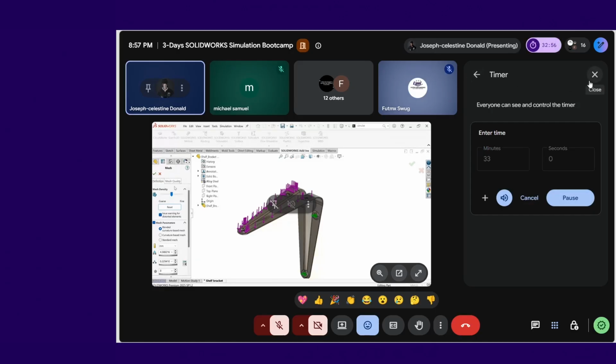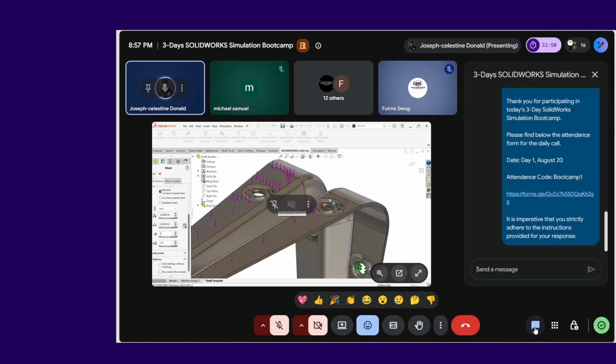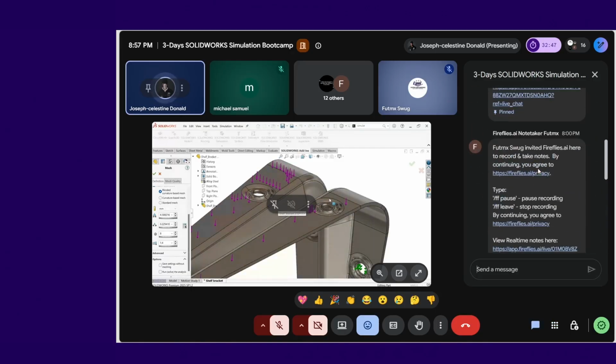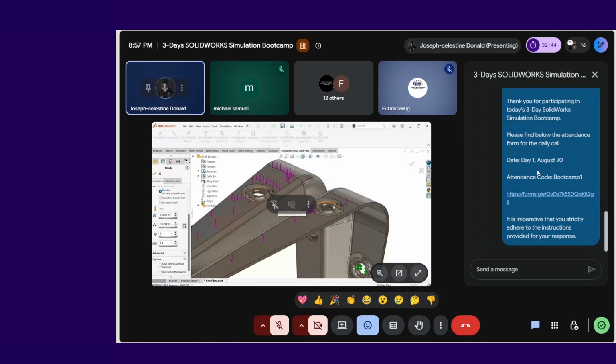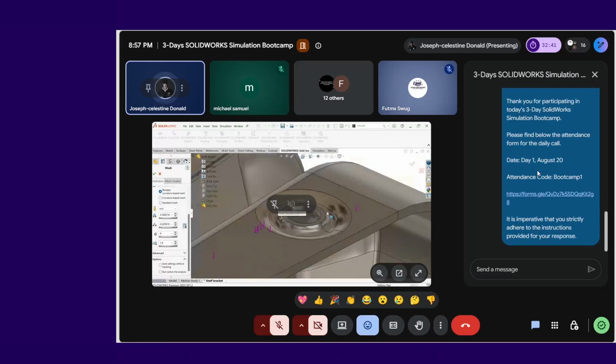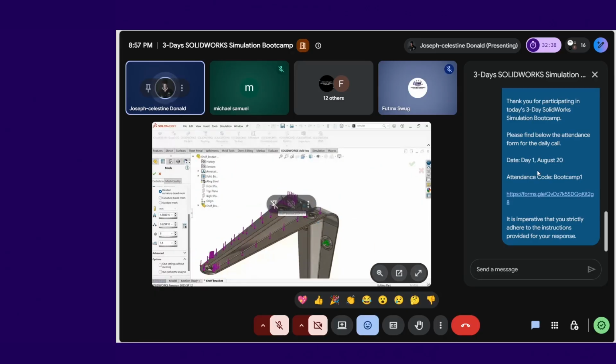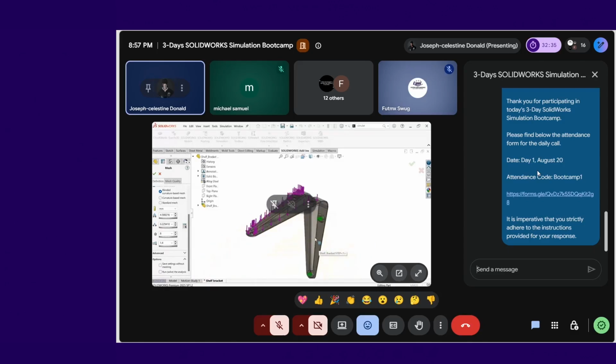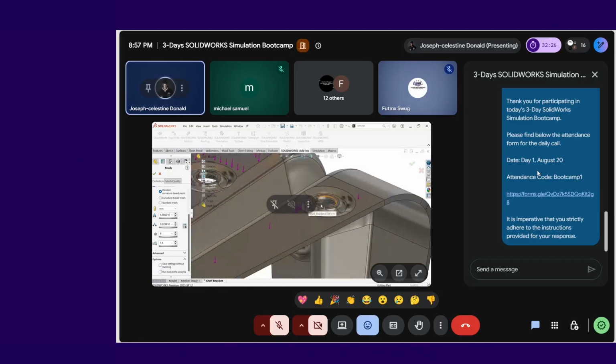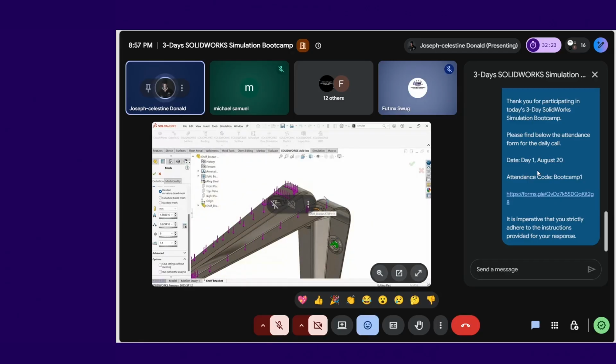Let me see. Mesh control is for situations where, let's assume the overall purpose of this design was to check for this specific point. Mesh control basically means you select where you want it. You don't want to run a fine meshing on the entire part, which we don't need. So you're focusing and saying the fine meshing should be on this specific part. That's what mesh control actually does. Don't waste computing time making the entire part ultra finely cut when it doesn't need it.